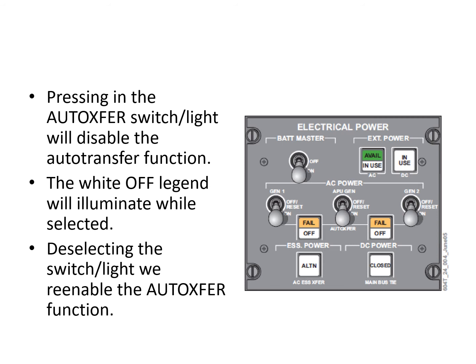The main bus tie, so the DC power switch is controlling that main bus tie, and if you put it to the closed position, if you push the switch in and close it, basically you connect TRU1, for example, to DC bus 2, and you lose the utilities.